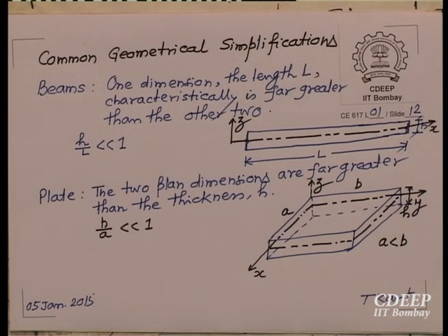Otherwise, it is moderately thick or thick, whatever you want to call it, there are so many definitions. So, geometrically a beam we call it thin if the L by H is something like 15 and above, then we can consider them to be thin. Geometrically, I am not telling you what happens in the interior of the body.